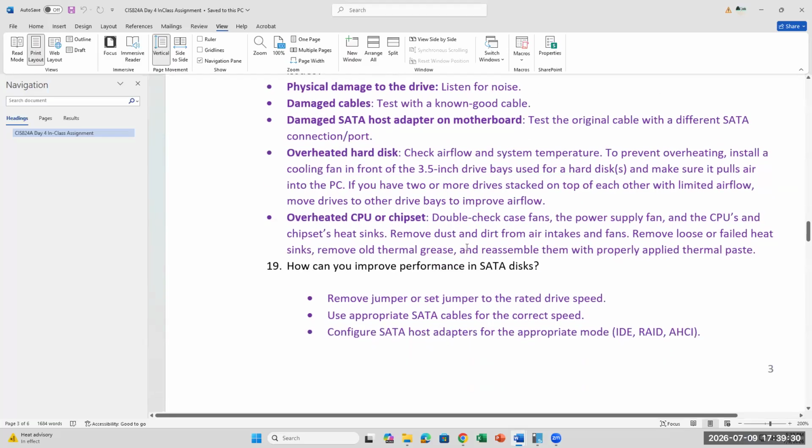So you should check your fans. You should make sure that there's airflow, that there's nothing impeding it, like dirt or grease. And then the processor also relies on thermal paste, because that's how it removes the heat. Also your heat sink, right? We saw that before. The thermal paste dries up after a few years, right? And the tube for it is less than $10. So you can get them. I like Arctic Silver, that's the brand. But like I said, there are generic brands that Amazon or other vendors sell that are good too.